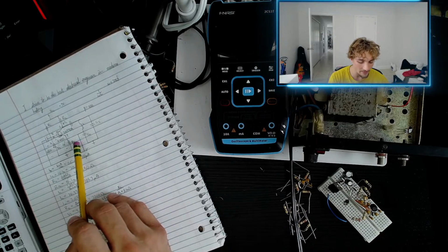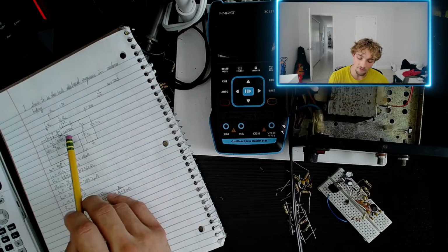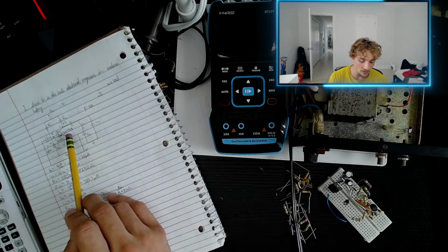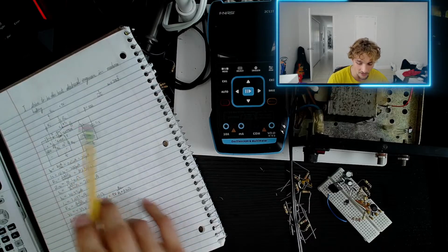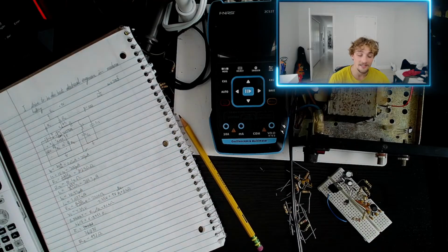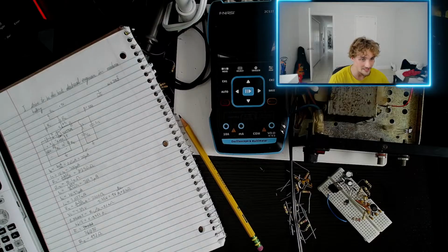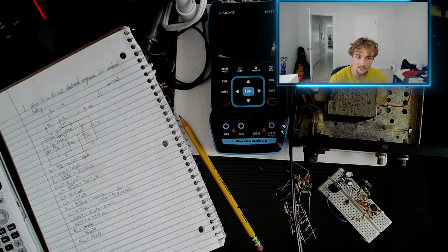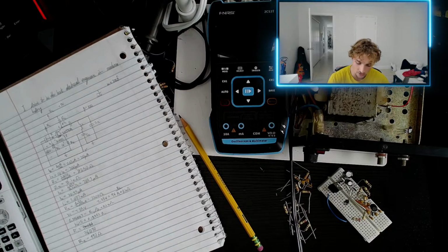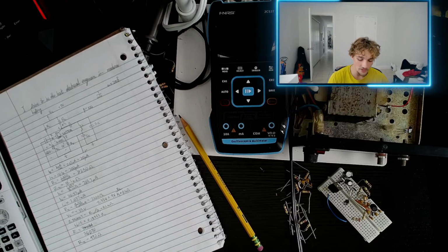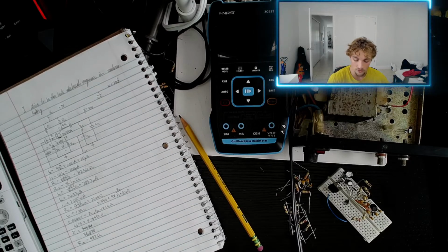It'll have a low impedance. Therefore, the high frequency signal will run across the resistor that is in series with the capacitor. And if that resistor is a far lower value than our emitter resistance, then we've increased our voltage gain. But there are limitations to this. So we'll continue with this analysis and see how much the emitter resistance affects our voltage gain.